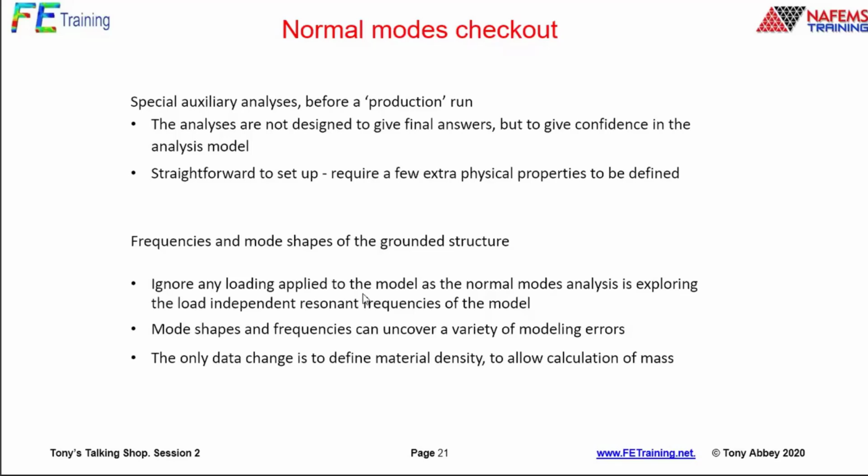Just switch the analysis type to normal modes. Ask typically for 10 modes. Just don't ask for 1 because that's not going to give you enough information. Just flip it to a normal modes analysis. Try it out if you've never done it before. We're looking for the mode shapes in particular, and that's all we're interested in.